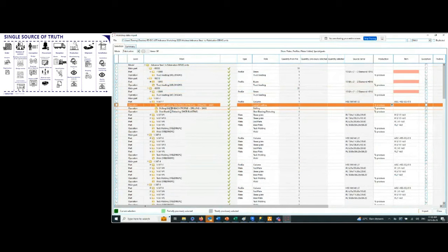Okay, so I can write rules to suggest that every time a bar element needs to be cut, first it should be going to, let's say, the beamline machine, the Python machine, whatever the case is, prior to maybe going to the manual saw. The manual saw I only want to utilize when I've hit critical mass. So you can write rules in the system to optimize the part routing at the import stage.